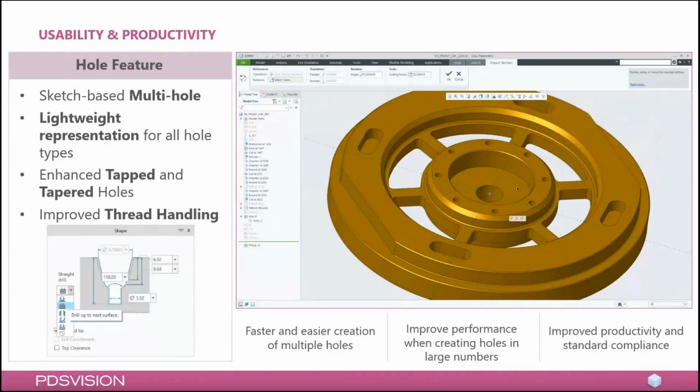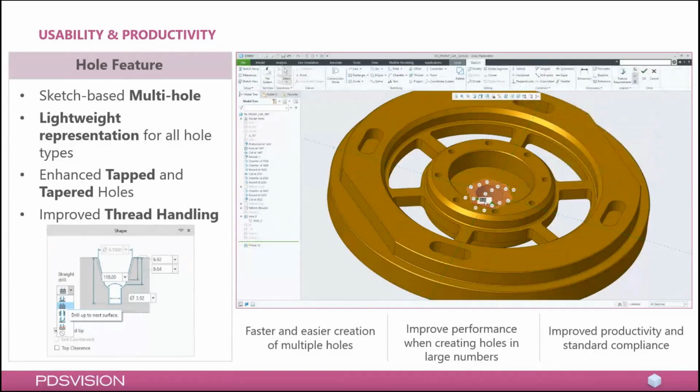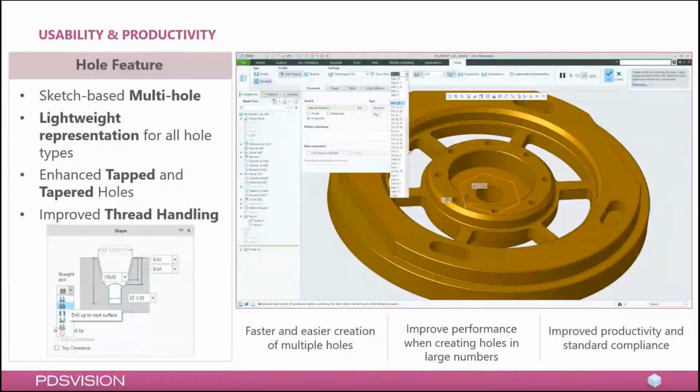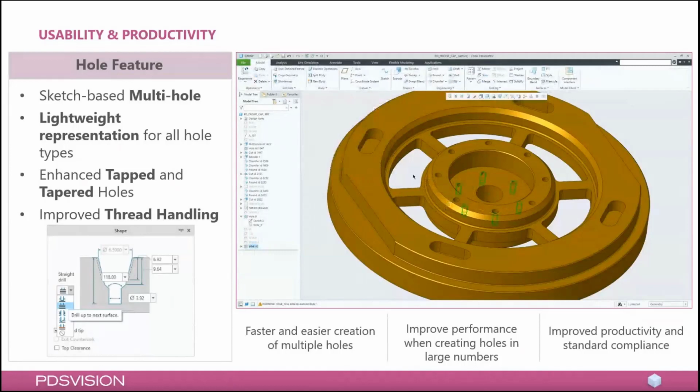In the video here, we are showing a polygon, and at each vertex of those lines there will be a hole. So at the line you don't have anything, but at the end of the line you will have a hole. If you need a complex drilling pattern or something like that, this makes it quite easy to create those drilling patterns and guide them with dimensions.